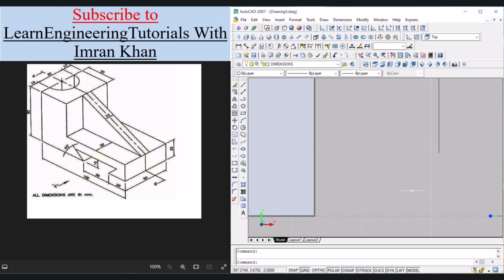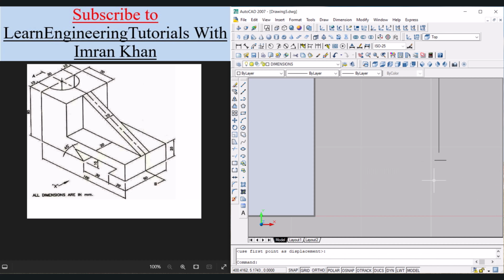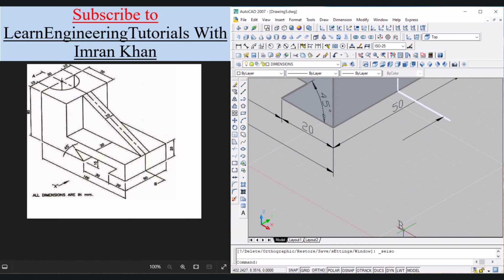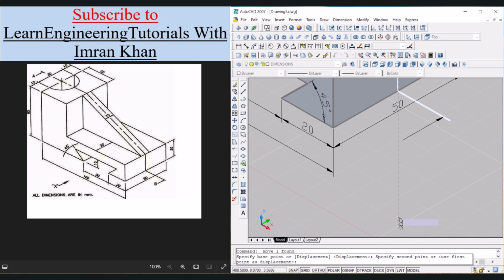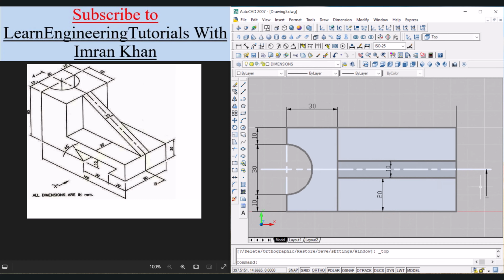So click on this B, move it, let this be the base point, and bring it in front of this line. Let's visualize it again in the isometric view. We can't see it properly, so click on this B, click on move, click on this point, and let's give it the height, so it will look in front of the arrow. Click. Now this looks okay. If you click on top view, now both are in line as well, and from the isometric view they are near as well.